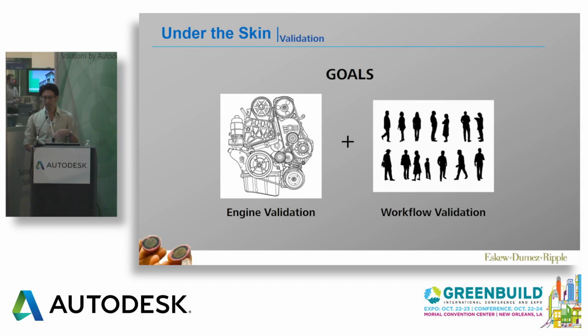And then the other side is the workflow validation, which is really about accuracy. These simulation programs are driven by two things: the underlying physics, and equally as important, how we use the tools as practitioners or as the actual end user. As we start to integrate a lot of these analysis inputs, a lot of the material specifications within the BIM environment, it becomes absolutely critical that we have a QA/QC process, right? That we know what we're specifying, so it's not just garbage in, garbage out, that we really understand what we're simulating.